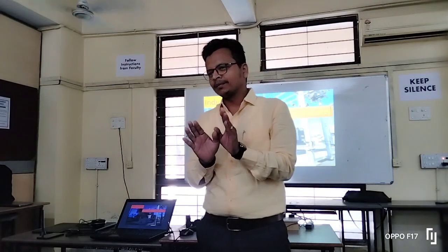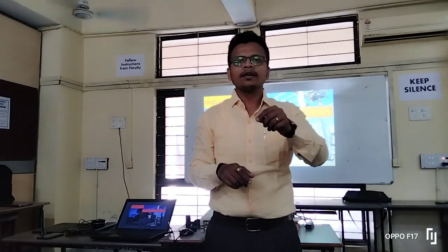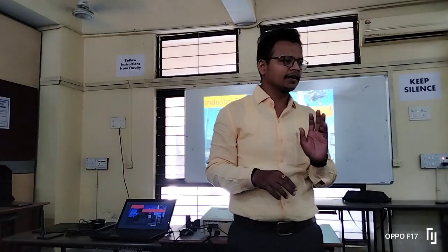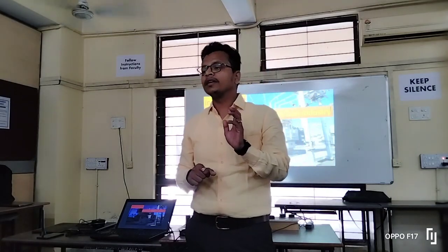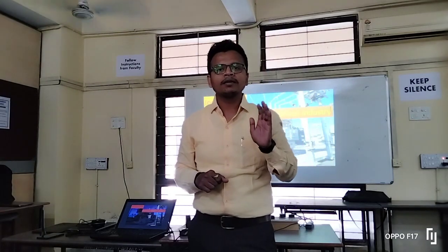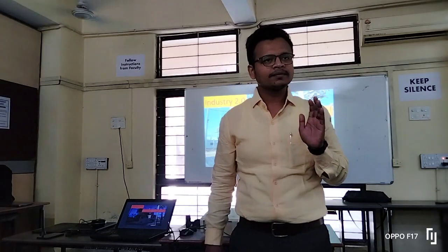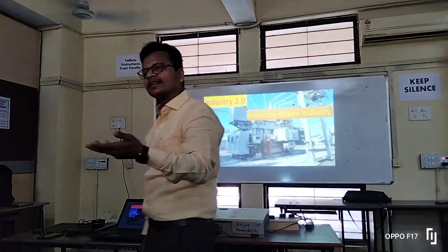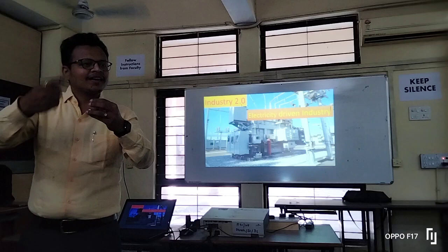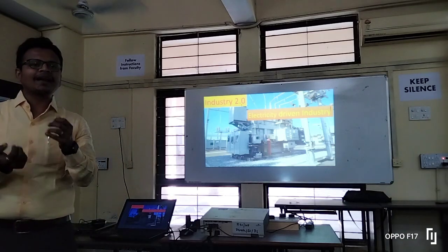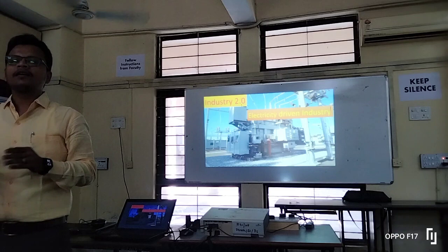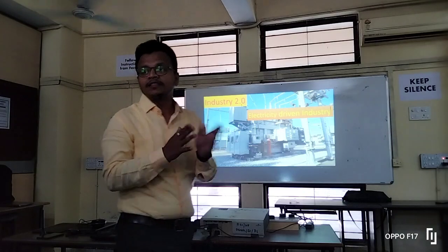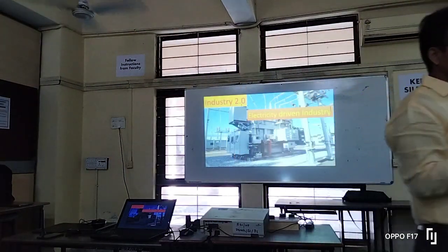What are those valves? It is similar to the tap at your home, but what is the difference? It is operated electrically. Electrically means using a solenoid. We already know the concept. What is a solenoid? It is an inductor, a simple kind of inductor. Coil. It will generate what? Magnetic field. And through the magnetic field, you will just provide displacement. Clear? So that thing will be there.